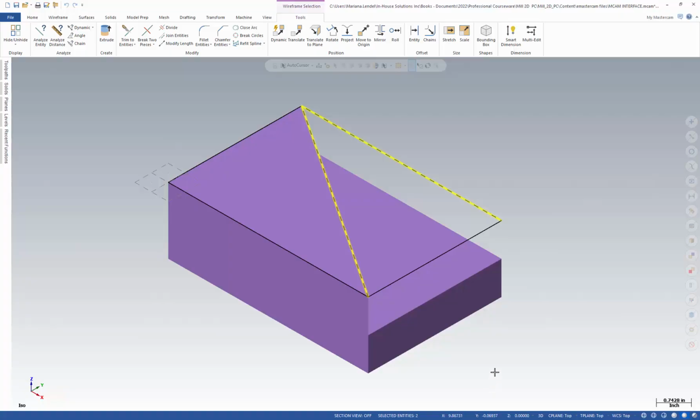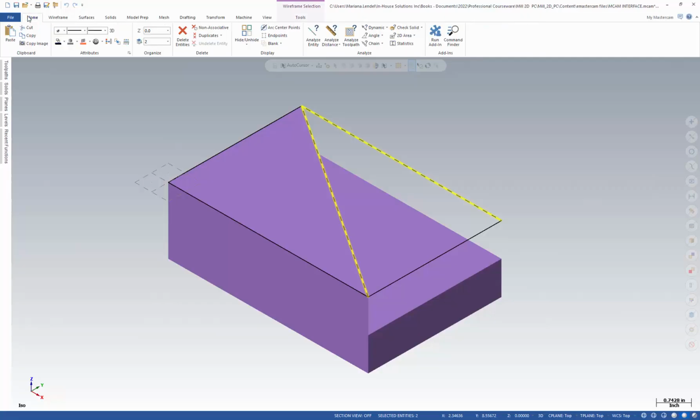It shows you the current location of the cursor, X, Y, and Z values. It allows you to set the construction mode to 2D and 3D. Remember, you can do that also through the right mouse click in the mini toolbar. Or in the Home tab, you also have the options here.